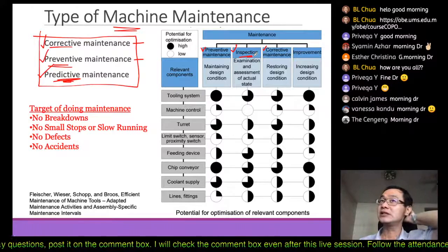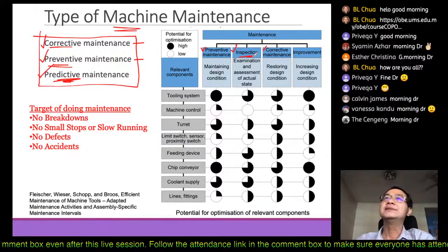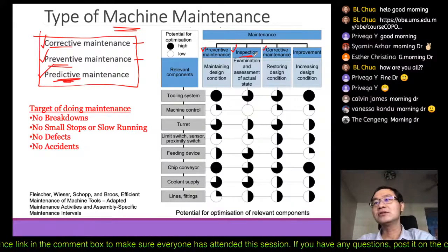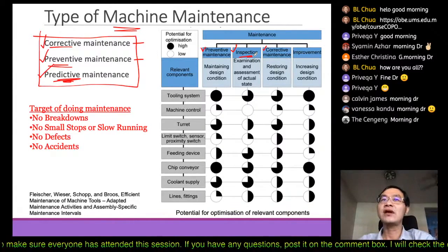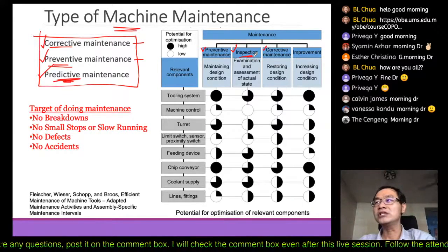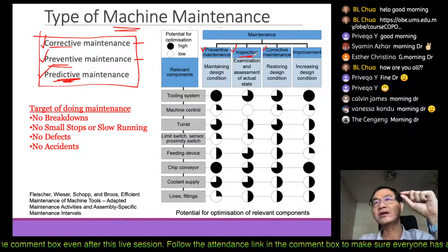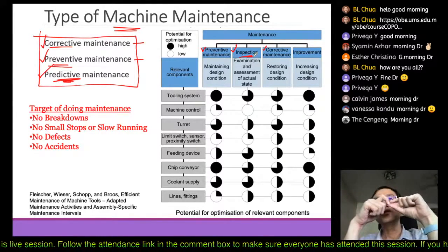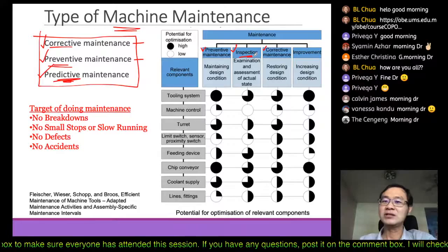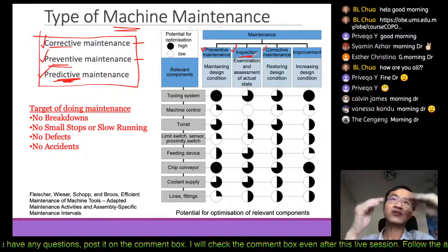So how do they usually do predictive maintenance? The easiest example would be a car wheel. So from a car wheel itself, whether we have to change our tire or not, we can monitor, right? You just go and inspect whether the rubber tread is still there or not. You just inspect. There is still maybe 2 millimeters depth of tread. Is it good enough? How long do we have to maintain it? So from there you can estimate.